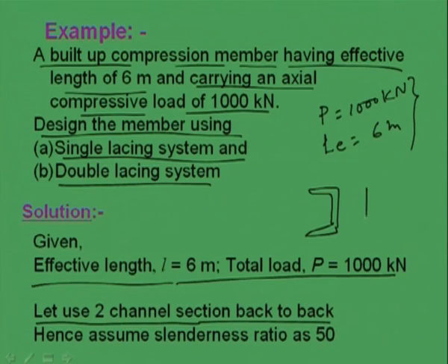So, we are using them back to back. This is the first criterion we are assuming. Okay. Now, from this what we have to do? Now, we have to find out the spacing through which the applied load can be carried without any problem, and second is whether it will be back to back or front to front. Now, generally back to back channel is preferable from the designer point of view. From the maintenance point of view, we have shown earlier why channel section back to back is preferable.